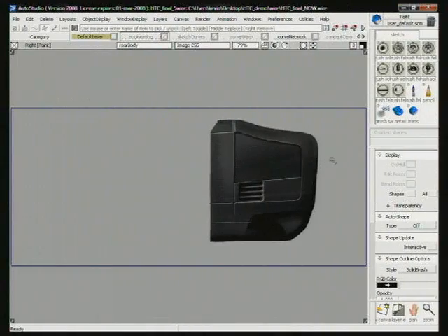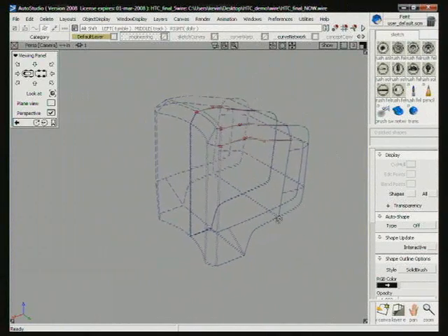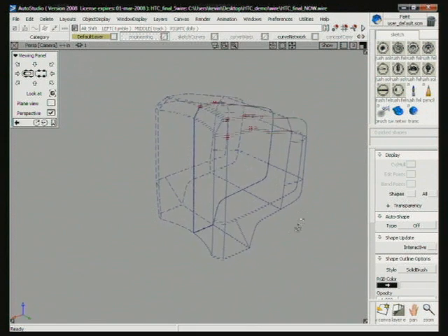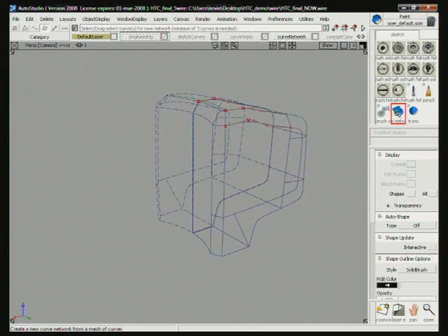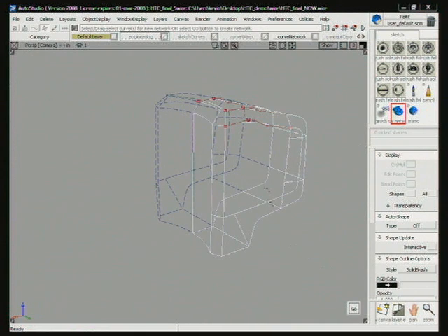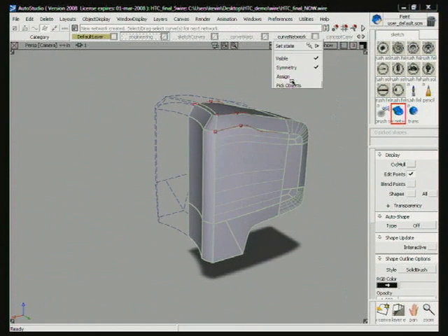Let's focus in on the rear housing. I'm going to use the same curves that I used for the original sketch to start laying out my model in 3D. I'm going to use a tool such as the Curve Network tool that will allow industrial designers of all skill levels to be able to model conceptual models very quickly. So I can go instantly from the curves to 3D.